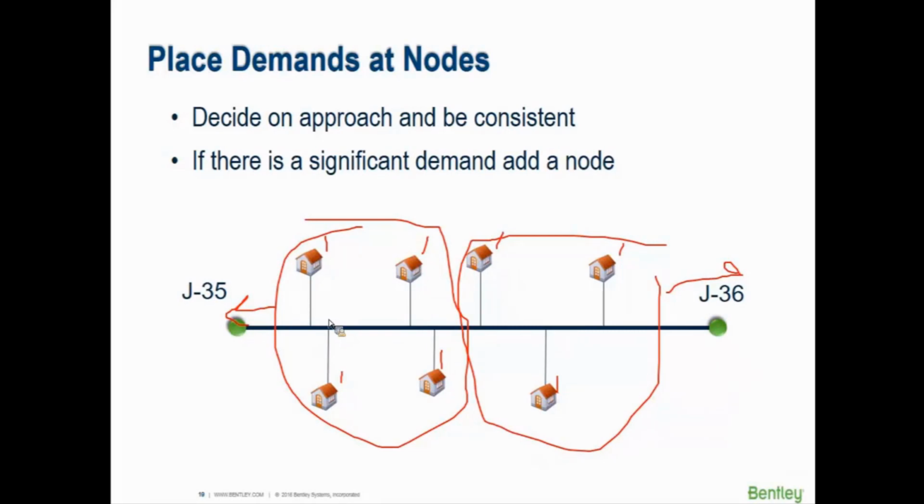But we also have customer meter elements that actually are like little houses. It's a little black house symbol with a chimney and everything, and you can actually place that wherever a meter is, and then have that connect to the nearest pipe or nearest node, meaning it would be referencing the nearest pipe or nearest node. So that way, exactly where the meters are, you have a symbol for the meters, which is a house or it looks like a factory or something, however you want to interpret it. And that's the demand that's going to be pulled off of the system at that point. And then you can specify whatever lateral size you want to use at that point. So that's a new element that came on a few versions ago.